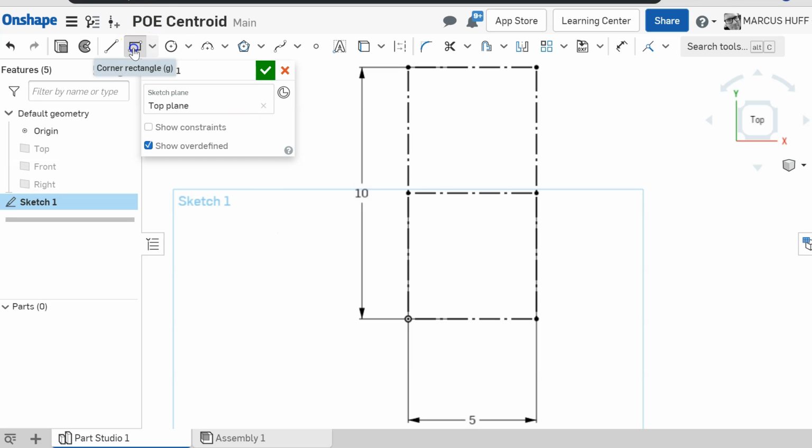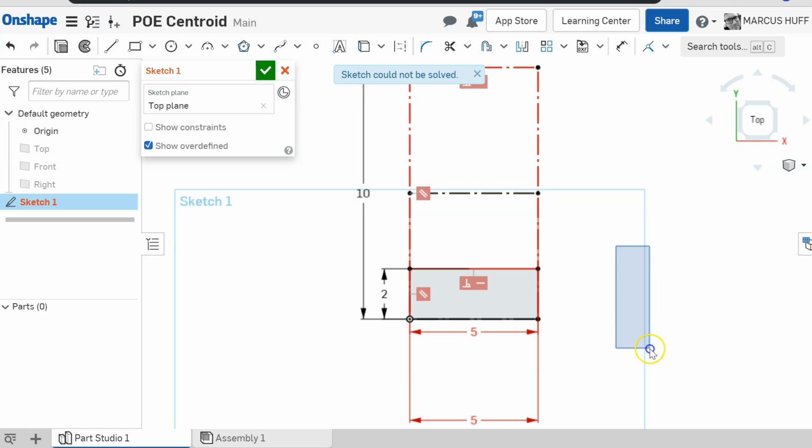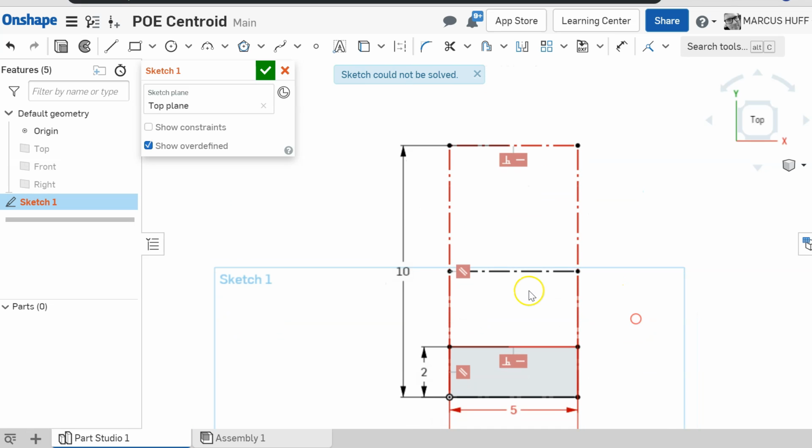All right, now the bottom square, I'm going to switch to object lines now, is going to be 2 by 5. So I should be able to click here. I did not get it, so I'm going to hit Control C. I should be in object line, and it drew a construction line. So starting at the origin, looking at my dimensions, okay, it's locked in on the 5. So the 5 is good, and I need 2 right here. Similar thing on the top. Okay, so that 5 is okay. It's complaining because it has a 5 and a 5 there. I don't know why it's doing that.